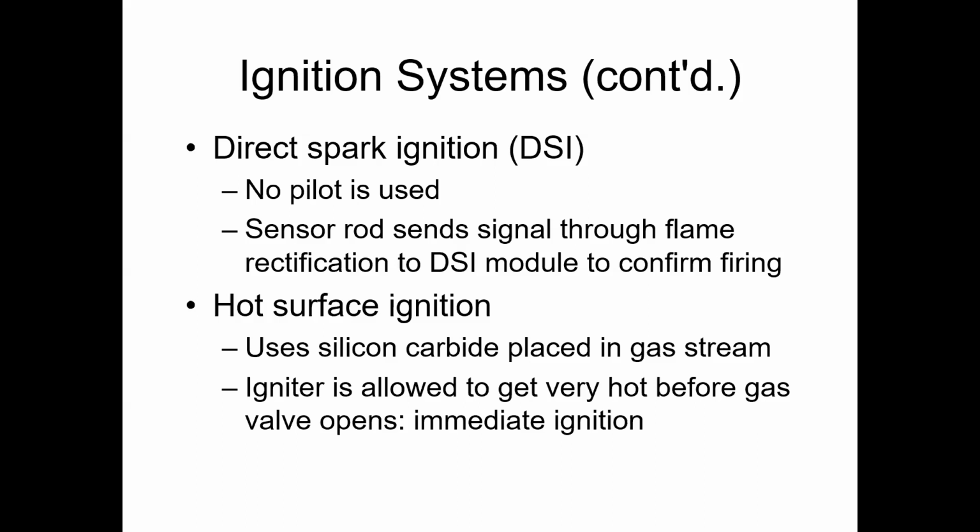But that's the advantage of this hot surface igniter: it just builds up resistance, ignites the flame, nice and safe. You don't have to worry, and you don't get that noisy sparking sound from a direct spark igniter. And if you've got a furnace that's near a living room or kitchen, it's a jarring sound when you constantly hear that clicking going on and off. If it's in a basement, who cares? It doesn't matter.